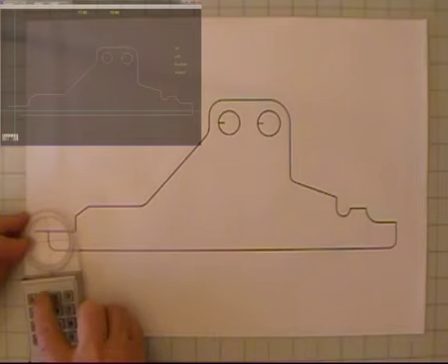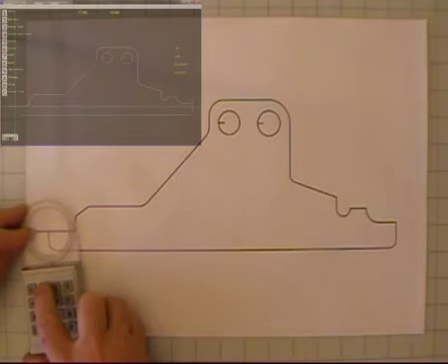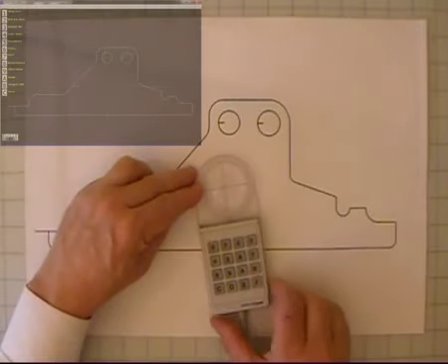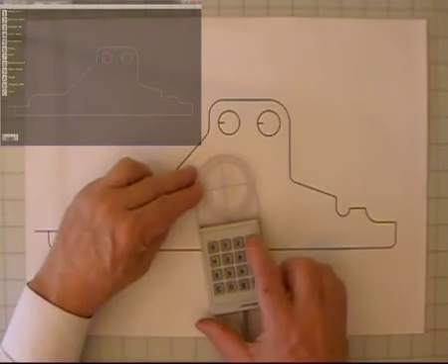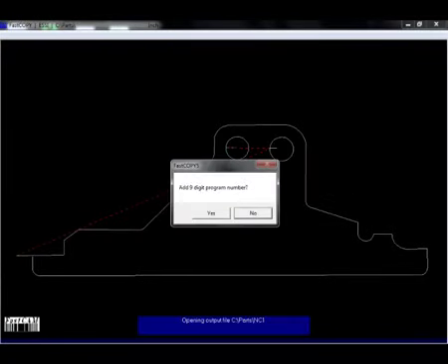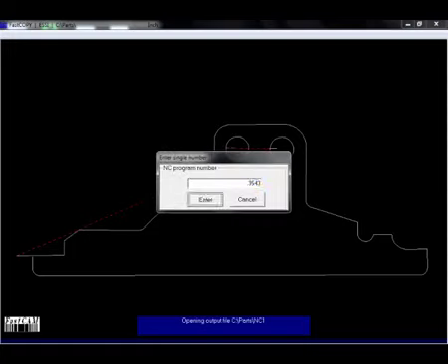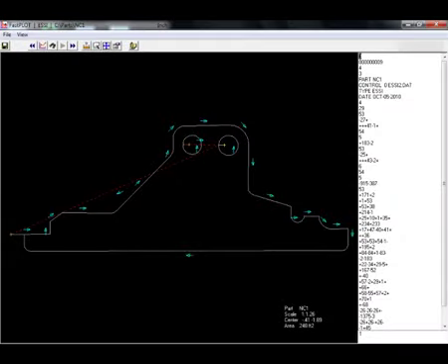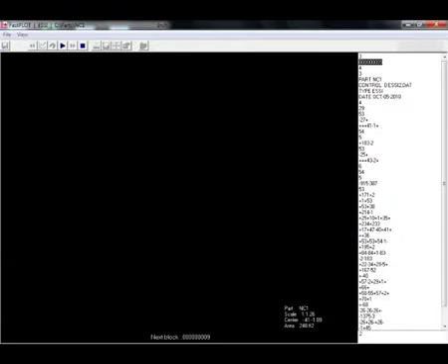You can output a DXF file now, but the real intention is to output your NC program and check it. To do so, press button number 3. The software is set up to output SE code, but you can output for a vast number of NC languages. The setups are identical with other FastCam family products. Using FastPlot, you can check your NC code automatically, even stepping through the movements.